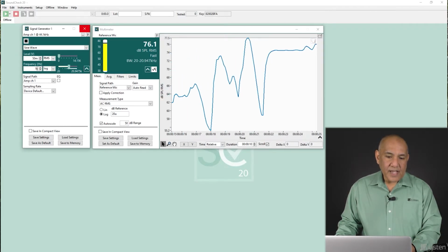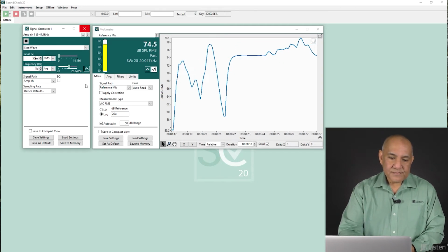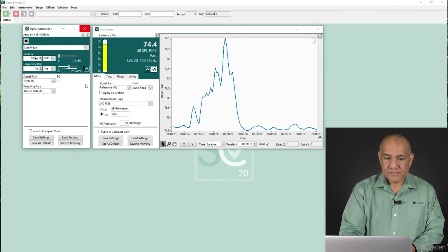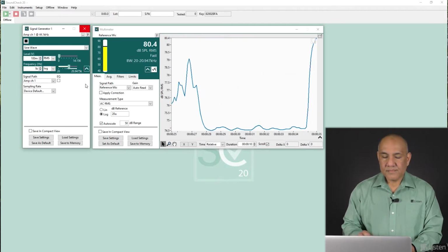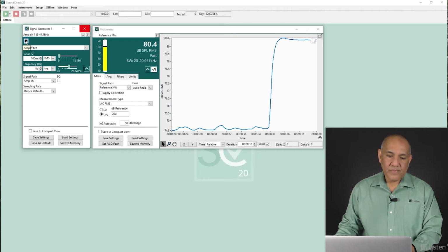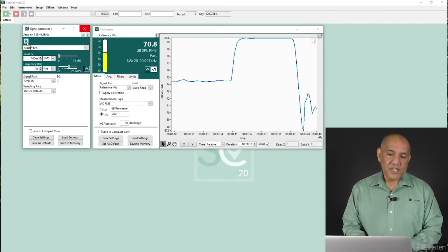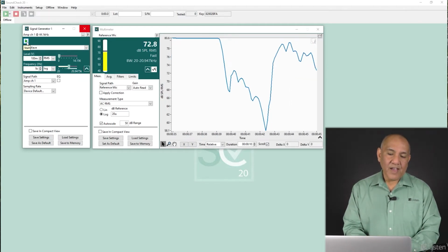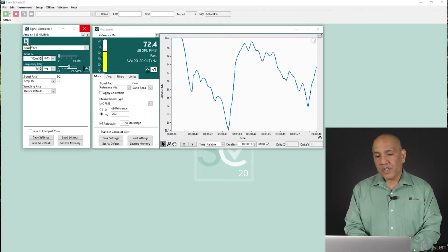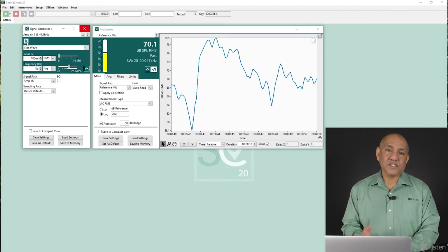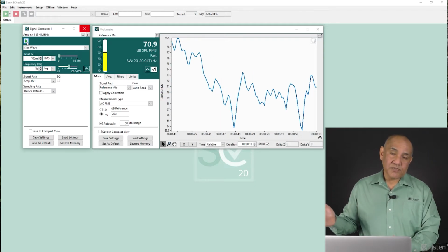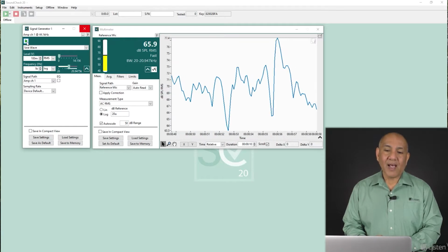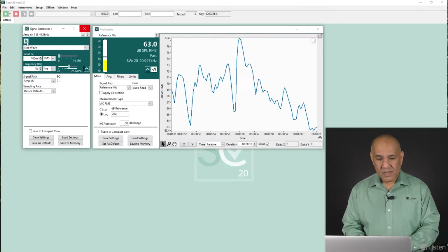And as I increase the level here, the strip chart recorder updates accordingly. So this would be very useful in an environment in any of the meters where you have to measure over time. If monitoring level, for example, I may start a test overnight and look for any dropouts potentially in the signal, or if there are level changes that should not be in a constant signal.